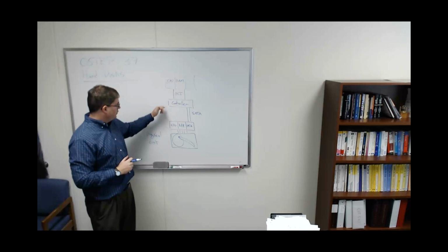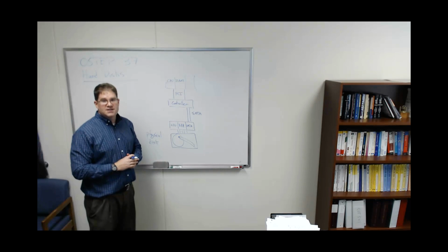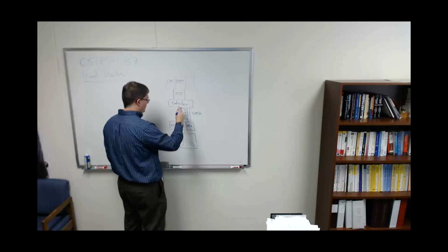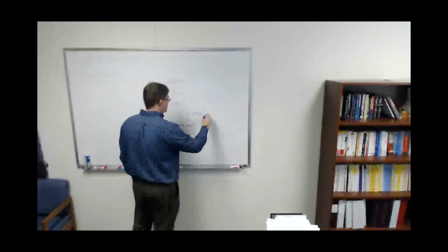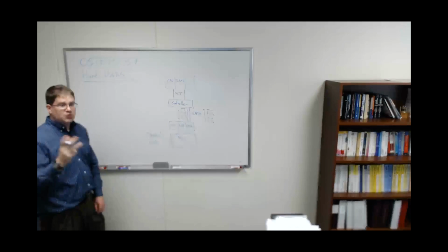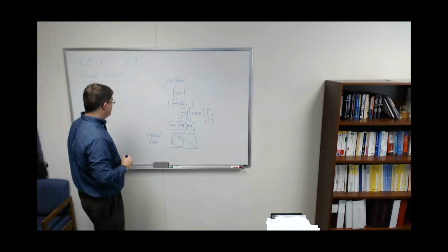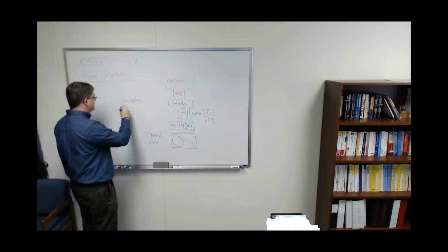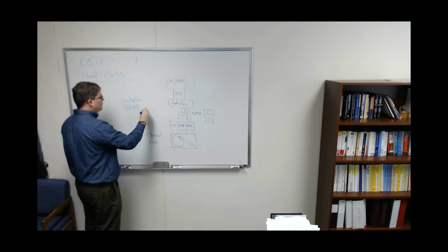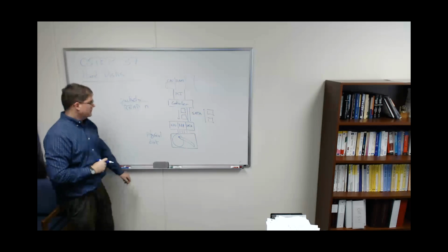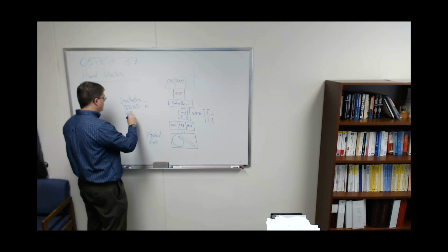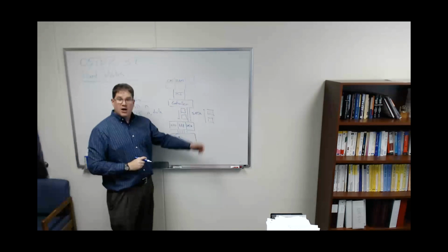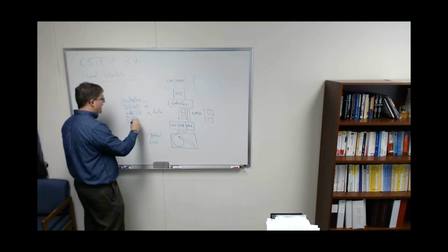So the way that this controller communicates with the disk itself is by issuing a series of commands in packets. So you can think of little packets of information flowing from the controller down here, and then responses coming back this way. And each one of these packets conveys what the controller is asking the disk to do. So one type of packet might say, read from block N. That's a request we would send to the disk. Another might be write to block N, along with some data. And a response that could come back from the disk might be, here's the data corresponding to block N.